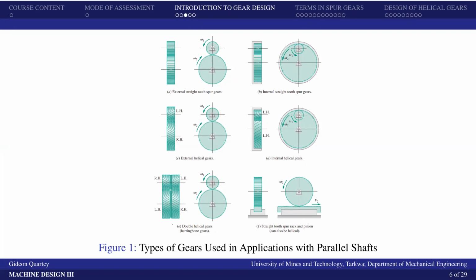All right. So that is the one advantage of the herringbone gears. And if you have been to the mining companies, some of them use the herringbone gear, especially for their ball mills that they use in grinding their ore material for processing. Some use these herringbone gears.